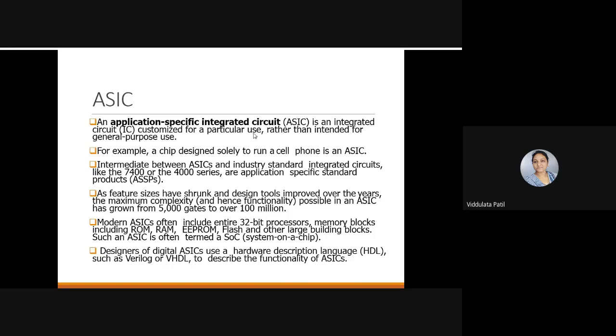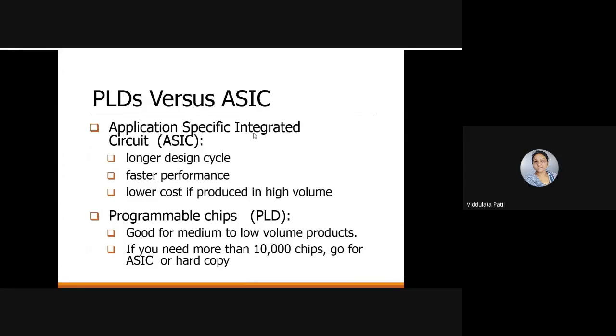So these are the different types of programmable logic devices. So our main interest now is in CPLDs and FPGAs. Okay, so now if we differentiate between PLDs and ASICs, okay, so ASIC, that is application specific integrated circuit. So here, as they have a number of gates as well as a number of functions they can perform, that is why it has a longer design cycle. Okay, but it has faster performance.